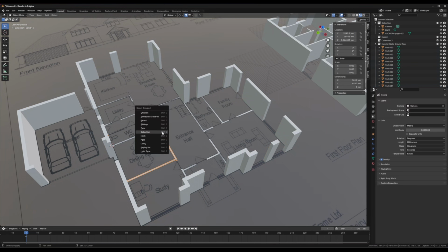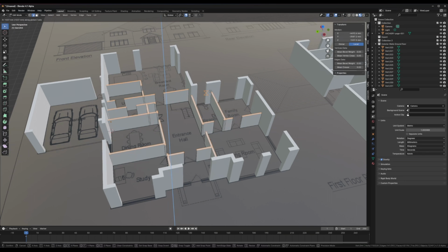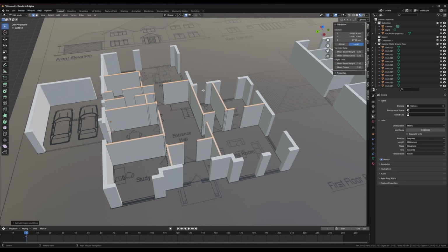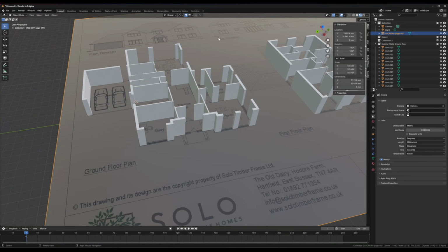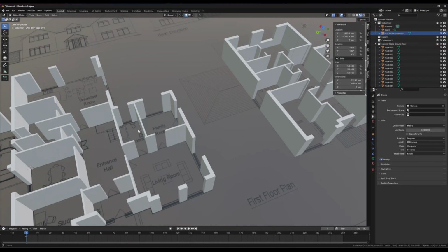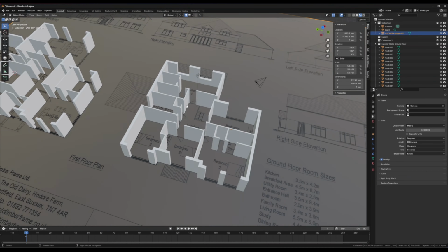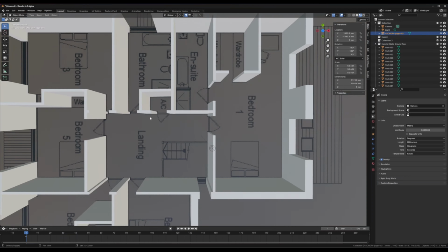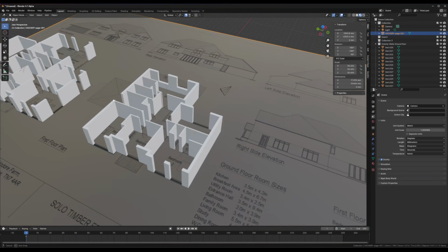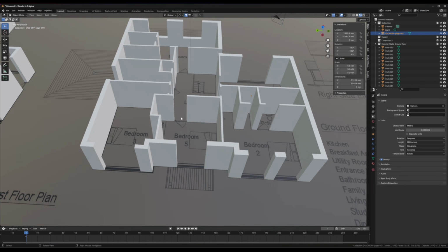And then press Shift G, select by collection, edit all, extrude up, snap it to the top edge, object, and now we have the ground floor and the first floor. Both interior and exterior walls are all done. So it's just the windowsills, then the center floor, stairs, roof, and then we're ready to bring it into Unreal for the first render for previs.